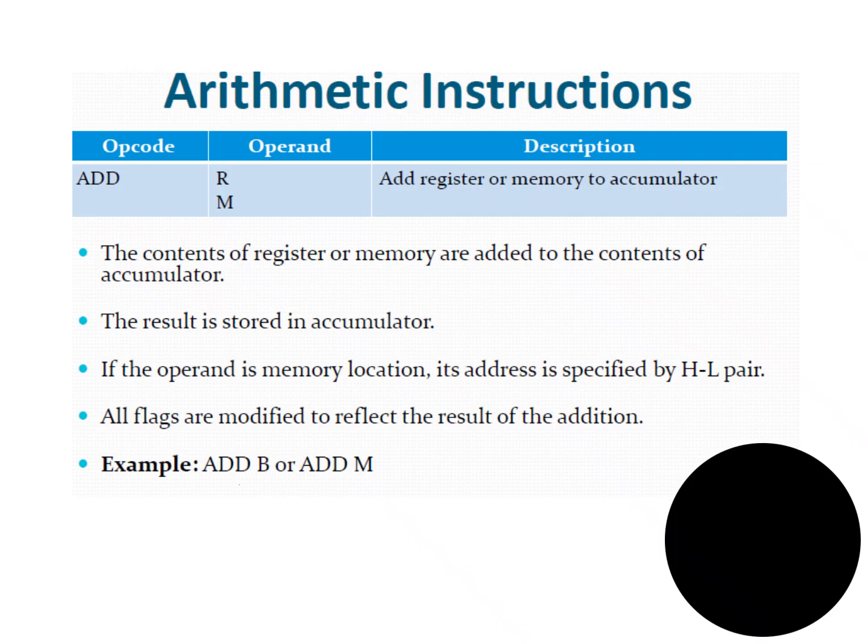Whenever you perform an arithmetic or logical operation, we need two sets of data. One of the data is represented directly here, and the other one will by default be in the accumulator. These two data will be added, and the result is stored in the accumulator. That is the function of the ADD instruction.